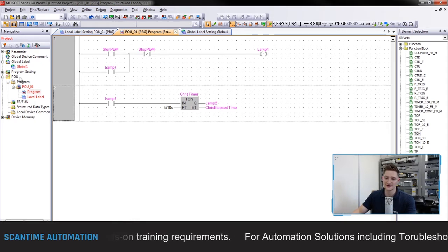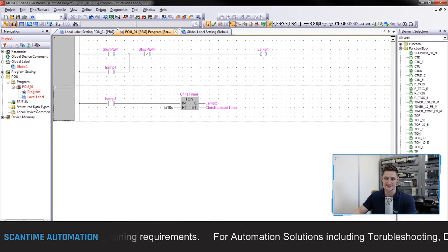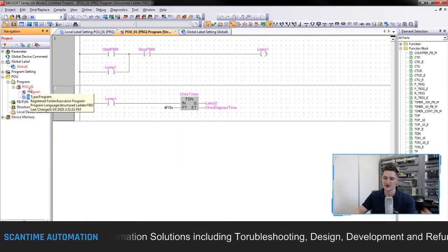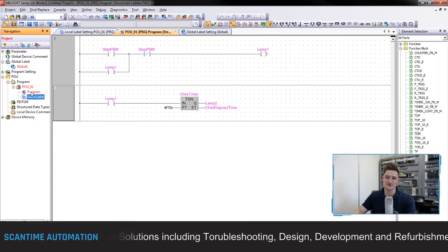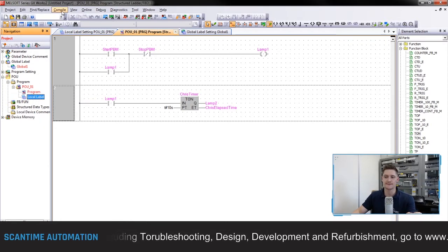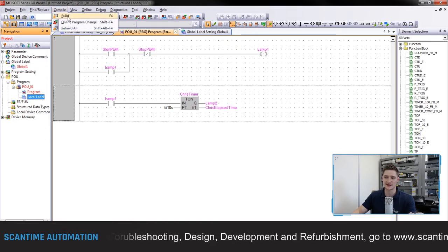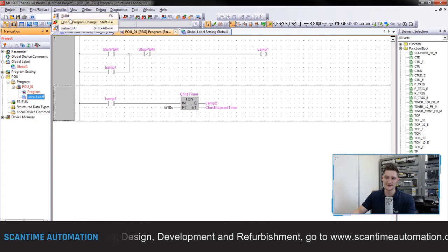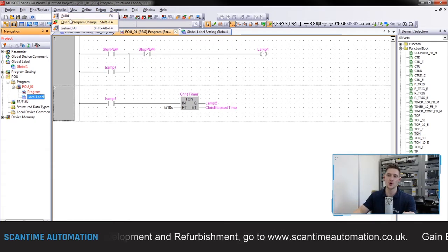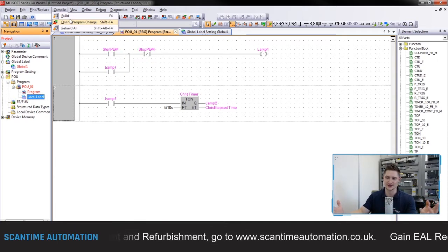Now, if you look on the left-hand side where my project tree is, you'll see that some of the folders and files are indicated as red. This tells me that these haven't been compiled yet. Now, to compile a project, you can go to the compile menu at the top and then select build, or you can go and do rebuild all. Build will simply just build this block only, whilst rebuild all rebuilds everything inside of the project.